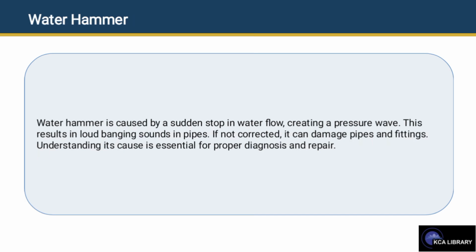Now let's look at the water hammer. What is a water hammer? A water hammer is a condition caused by a sudden stop in water flow, creating a pressure wave. This results in loud banging sounds in pipes. If not corrected, it can damage pipes and fittings. Understanding it is essential for proper diagnosis and repair.